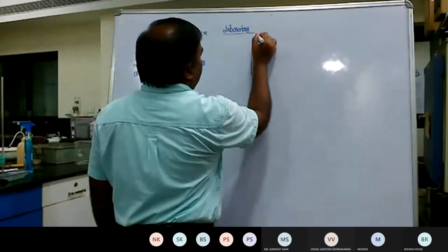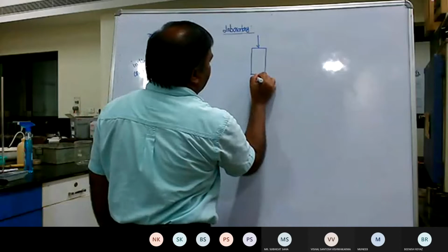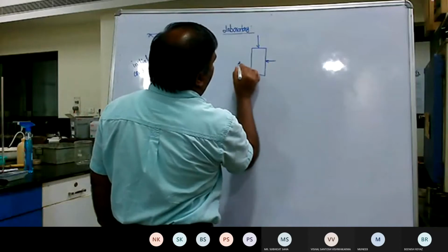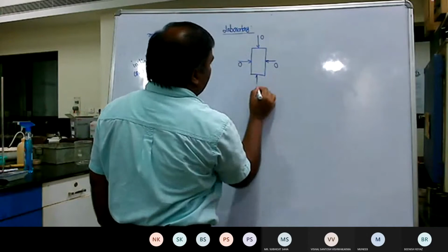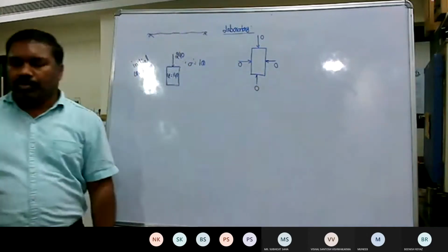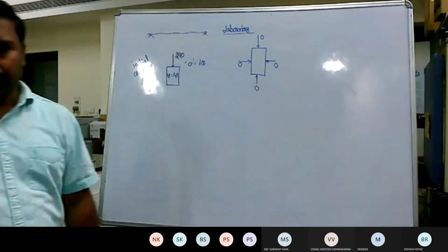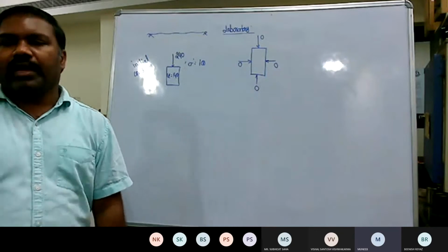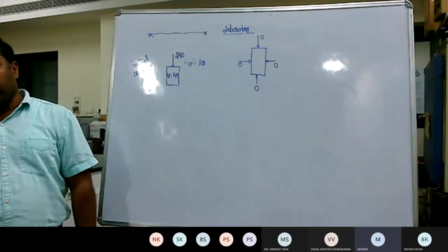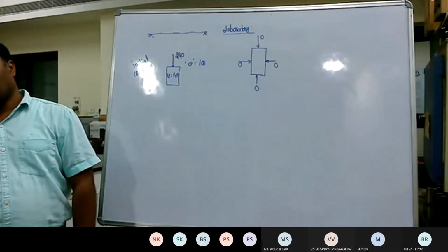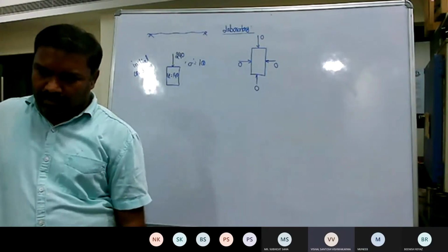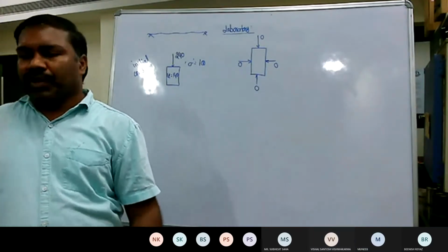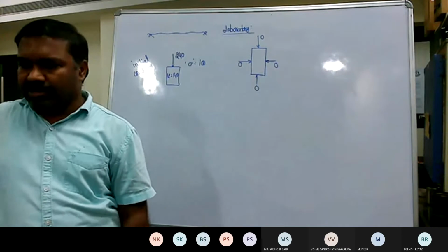First of all, the axial and normal stresses that will act are 0. And what would happen to the pore water pressure? Negative pore water pressure. And how much is the value? Minus 140 kilopascal. Okay. But before that, you have to read the statement of the sum once.